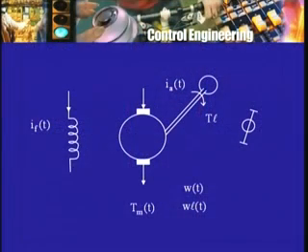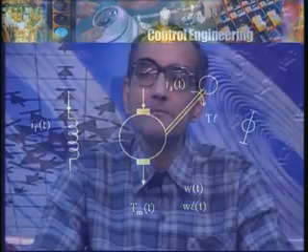We can think of the load as something which has to be rotated, and that requires some torque to be applied to the shaft. So this torque is referred to as the load torque. So for the symbol we will have T, capital T with subscript small l. That's the load torque. What's the difference between the torque produced by the motor, Tm, and the load torque, TL?